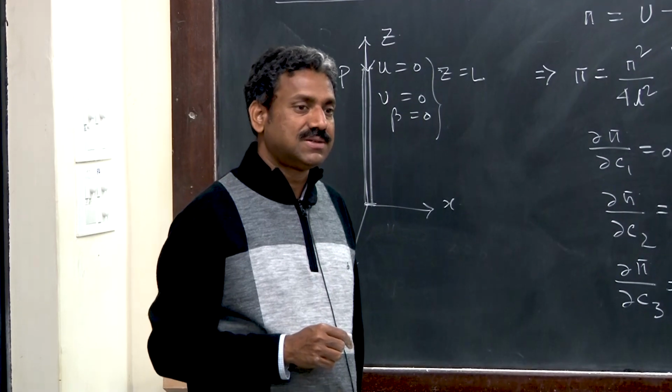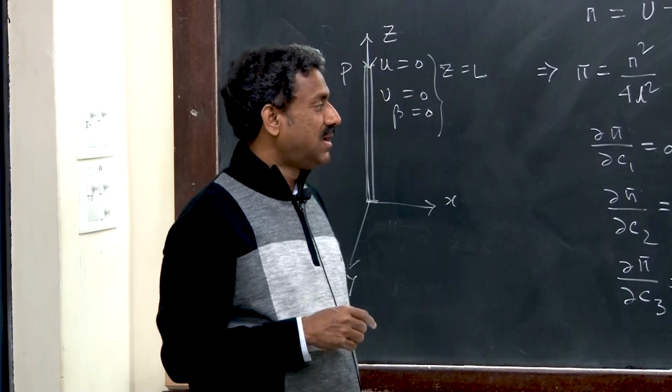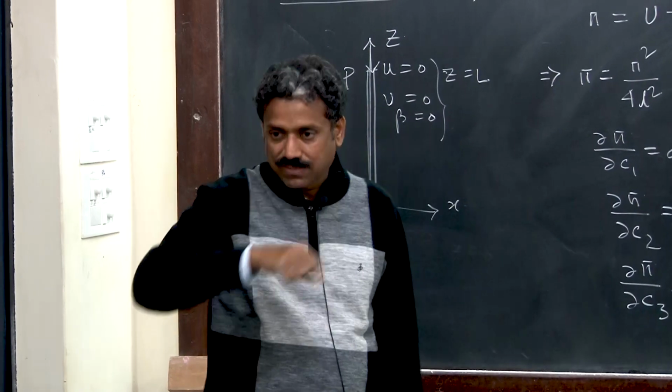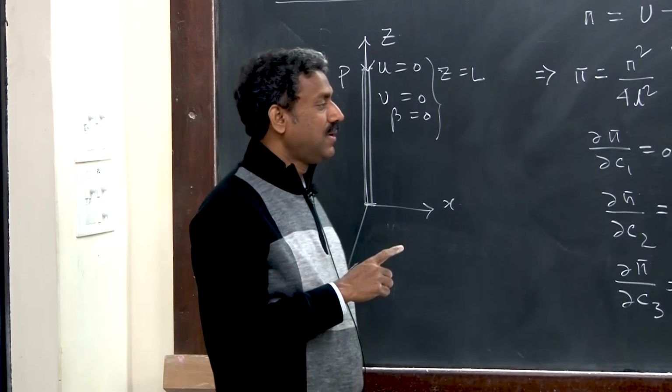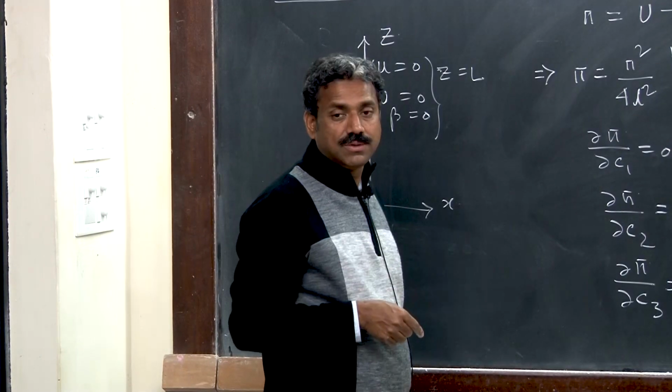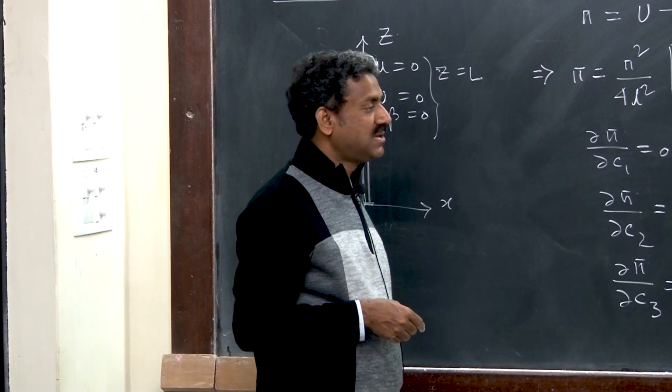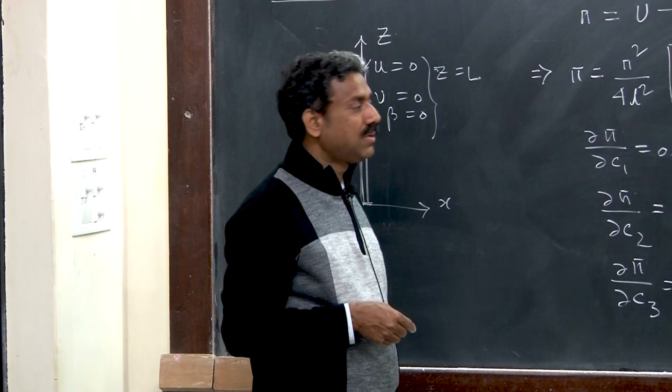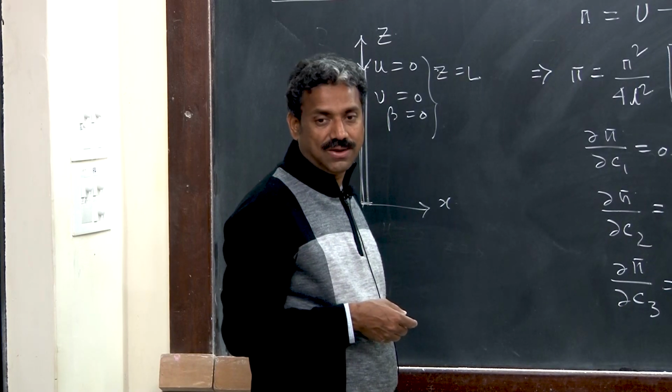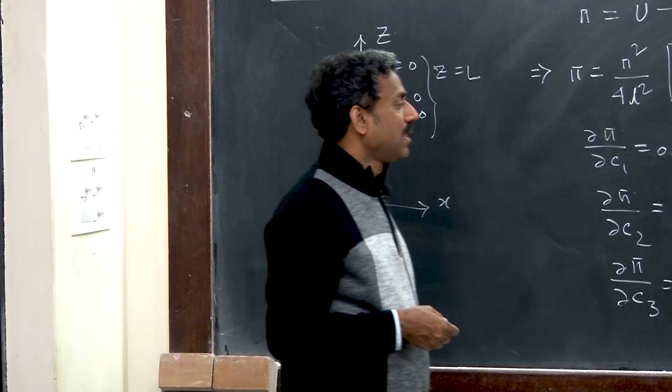We started with the flexural buckling. Now we started with the torsional flexural buckling of column, right? So this leads to a homogeneous system which is an eigenvalue problem, right? The determinant must be 0, right, for a non-trivial solution, and that's where we get the critical load, okay.